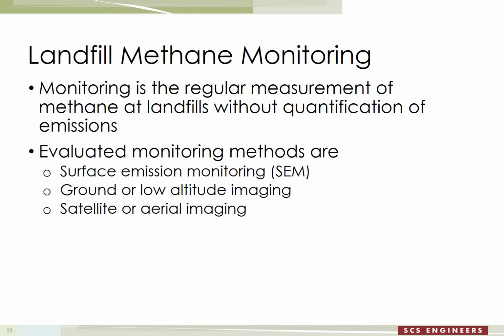So the third component is landfill methane monitoring. These are techniques that don't necessarily try to estimate or measure the emissions, but rather just measure the concentration of methane above the surface of the landfill as a means to determine where emissions might be occurring, where we might have hot spots. We're going to look at the traditional surface emissions monitoring methods that are built into the federal and state regulatory programs. We're going to look at both ground level and low altitude imaging, as well as satellite and aerial imaging.